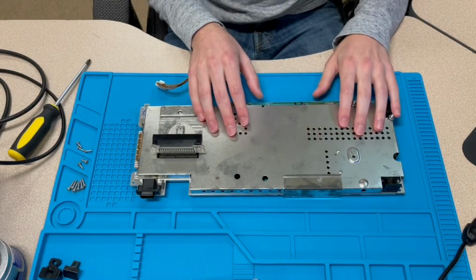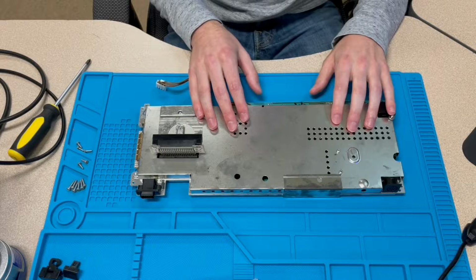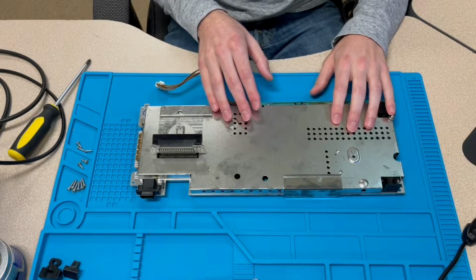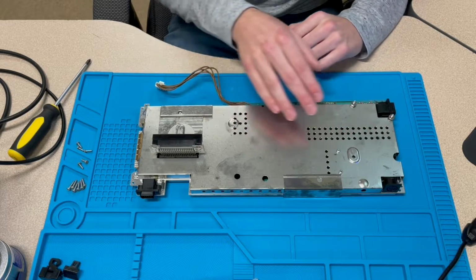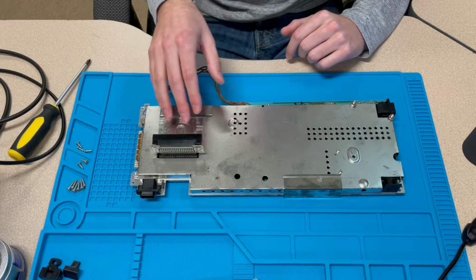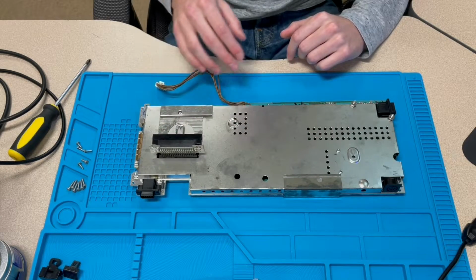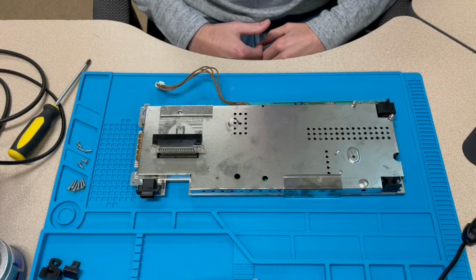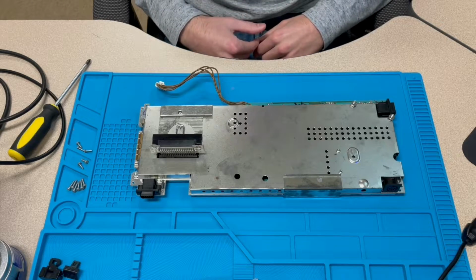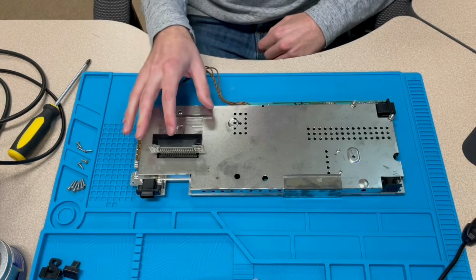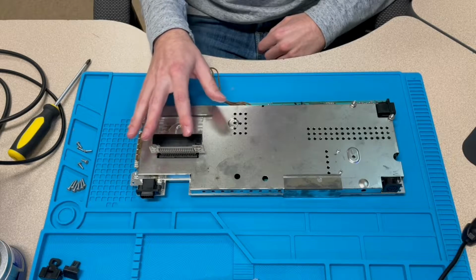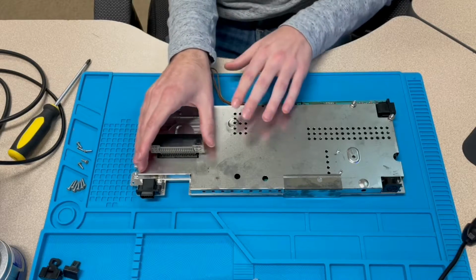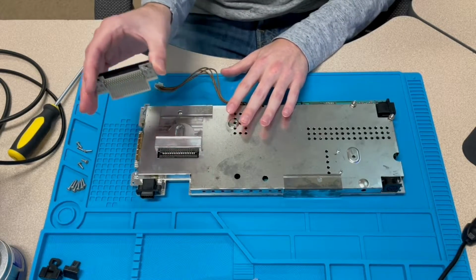So here's the motherboard assembly from this computer, and if you saw the video where I repaired the last one, it looks totally different. The other one does not have a shield above the top of the motherboard like this one does. So there's a little bit more you have to do to get to the motherboard of this computer. And the first thing we have to do is remove the cartridge slot header. It's just hooked into a connector on the motherboard, so it should just pop right out like that.